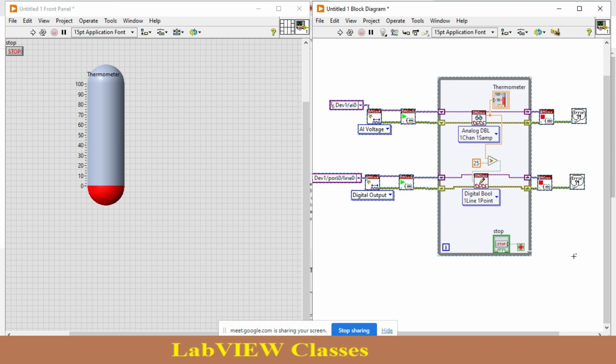No, sir. It is a ramp test. Initially the temperature increases, then holds for a particular time, then is reduced, and then the cycle will be continued. Mainly it is both increasing and decreasing. So for that purpose, you need another signal also. One is for AC and another one is for another device that may be a heater, because you want to increase and decrease the temperature.